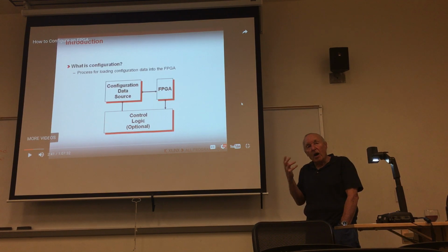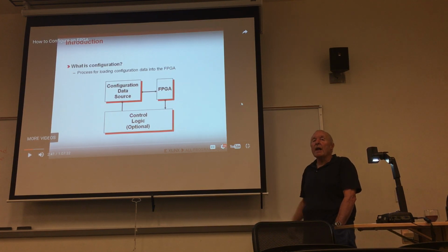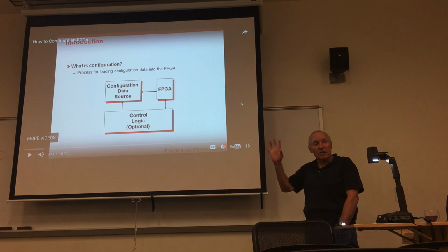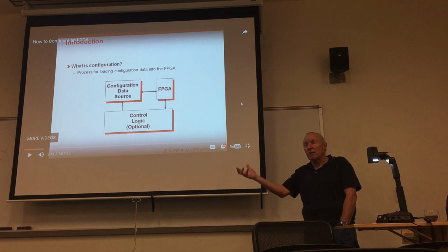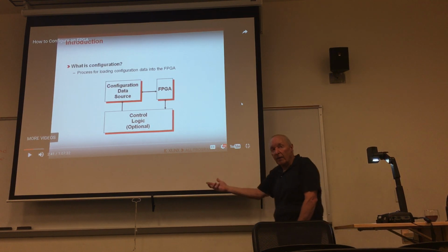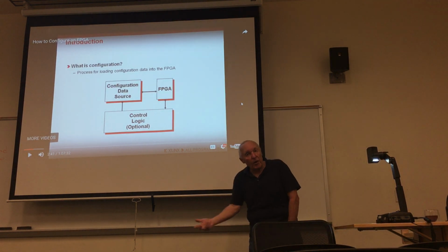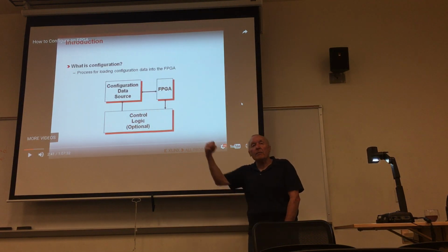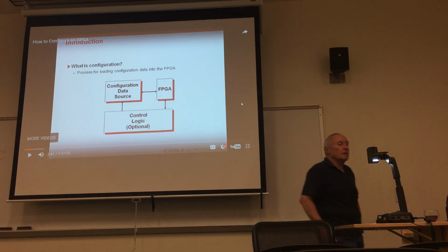So somehow on the printed circuit board, I've got to provide a means of configuring, of programming the FPGA. And so he's going to discuss in here 4 different ways that that can be done, where you could have a standalone system, a medical instrument, a smartphone, or whatever, SRAM-based FPGA, you power it up, and it automatically gets configured.